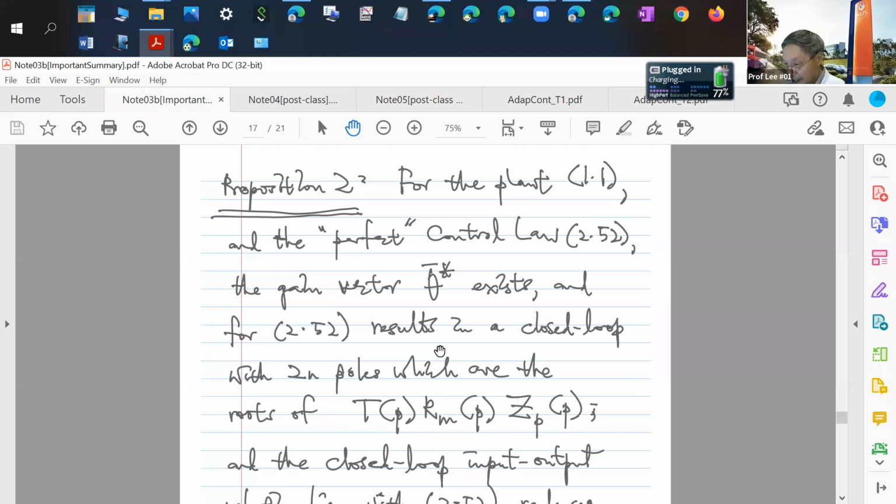TP is chosen by you because you set up the 1/T filter. RM is your reference model, also chosen by you. Certainly, this part is not much of an issue because these are design polynomials and you will choose them to be stable. So no problem at all.